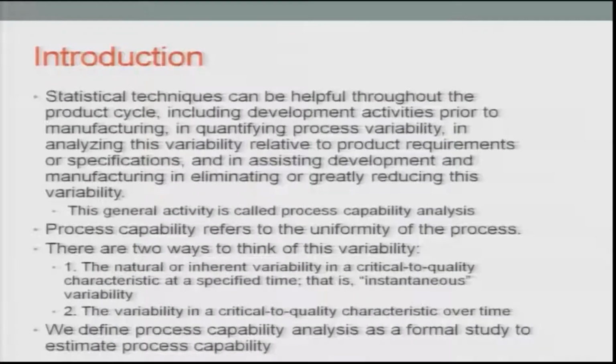So, now we will continue some discussion about the statistical techniques in further detail. Statistical techniques can be useful throughout the product cycle, including development activities prior to the manufacturing process, in quantifying process variability, in analyzing this variability relative to the product requirements and or specifications, and in assisting development and manufacturing in eliminating or greatly reducing the variability. This general activity is called process capability analysis, and when the process has started,